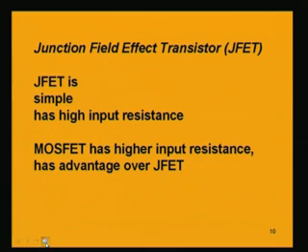It has also high input resistance, because in MOSFET we have seen that the input resistance is very high. The JFET is also a device which is having a high input resistance, but this input resistance of the JFET is in fact less than the input resistance of the MOSFET. And also there are some other advantages of the MOSFET device, because of which actually the MOSFET is gaining popularity, and this JFET is going to be obsolete day by day. But still we will be discussing JFET a little.